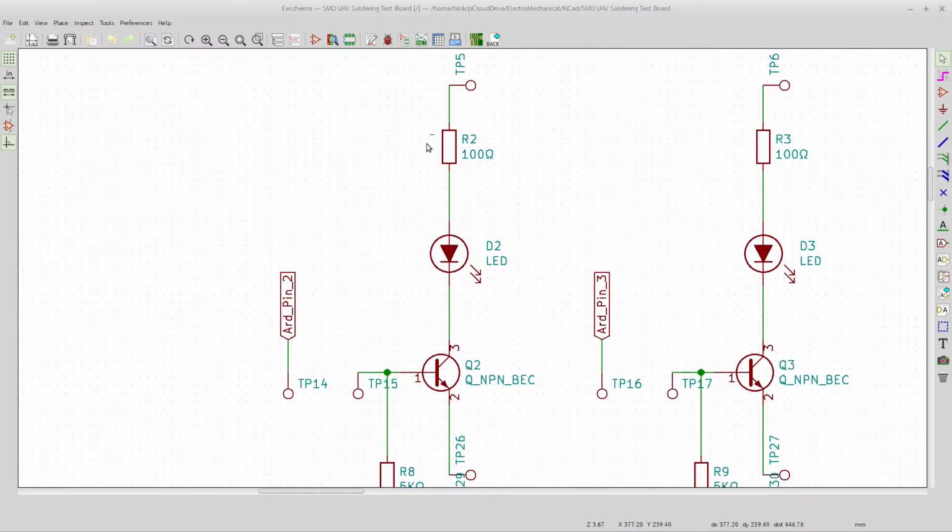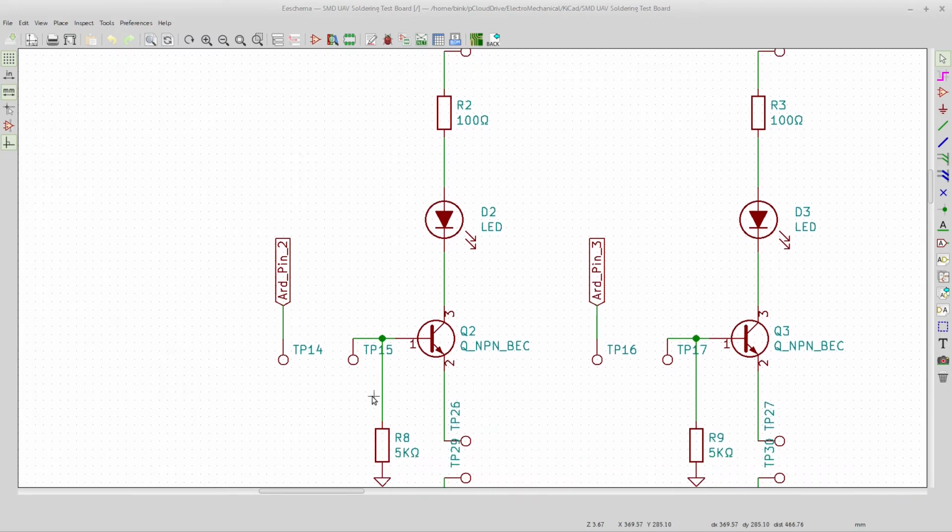This is a current limiting resistor for this LED. This resistor and this resistor down here are the same thing. They're the same construction. They almost look exactly identical, except for the numbers are different. But we call this a current limiting resistor because of its place in the circuit. It's resisting the flow of current, resisting to keep the light from being too bright and damaging itself, and we can increase it a little bit more to maybe dim it down.